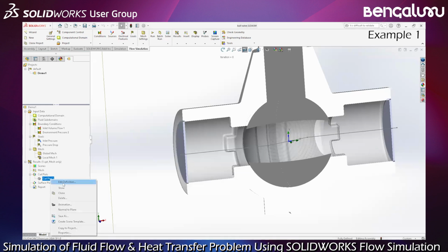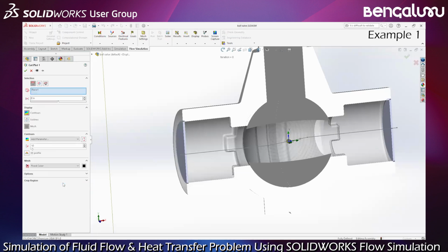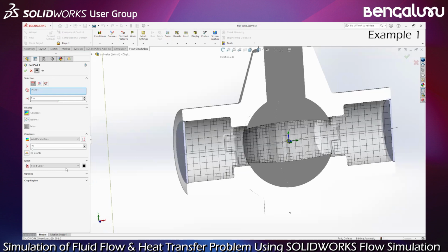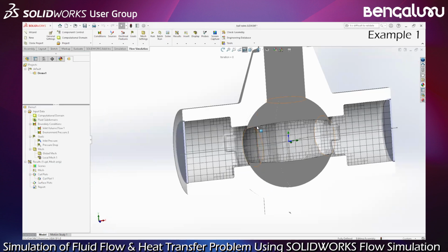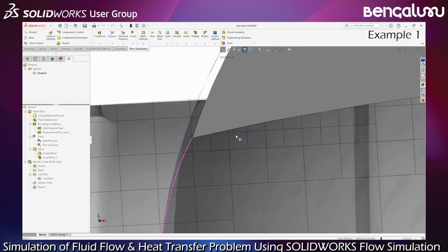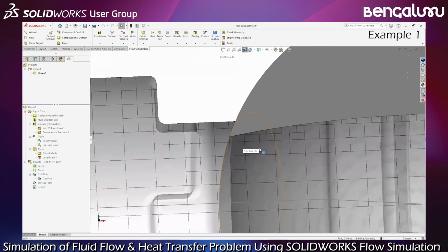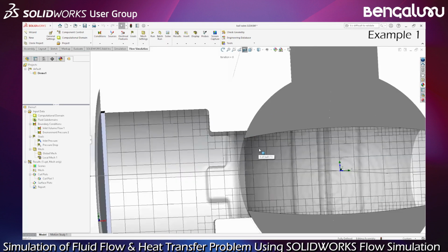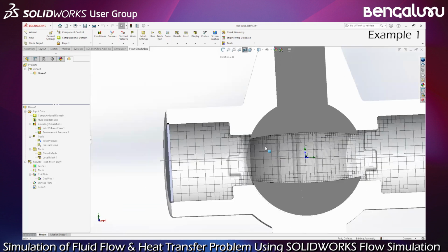And if I use the cut plot, so I cannot have contours, but I can have the mesh. And if we look there, it's a bit better, but not enough. Okay, there is additional refinement. If you remember, I had only one cell there, but maybe we can go further. Even, I mean, here I selected the valve, I can select a point, I can select whatever. If you need to refine this mesh, again, I can.